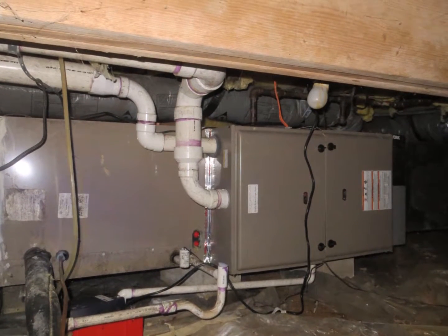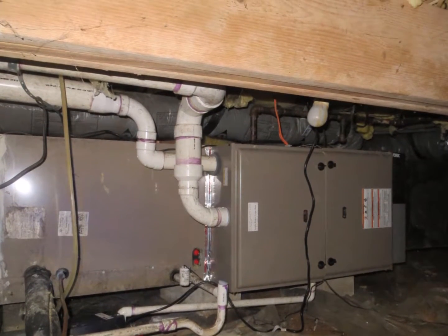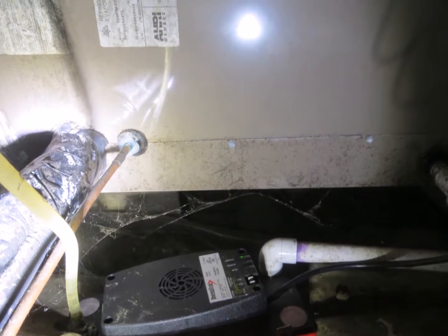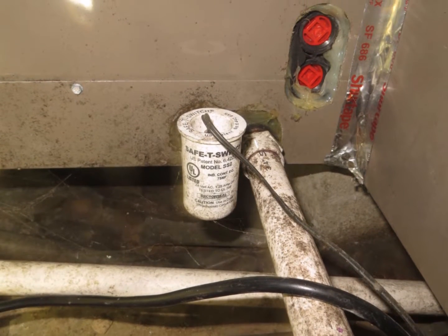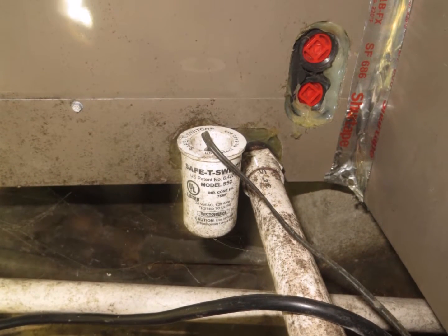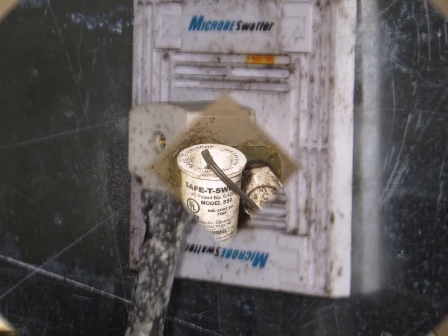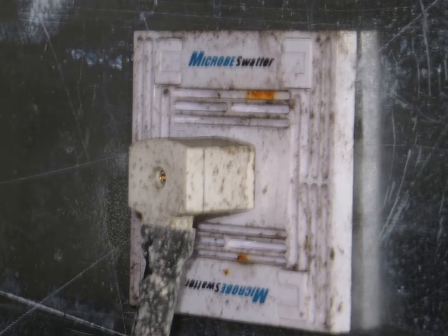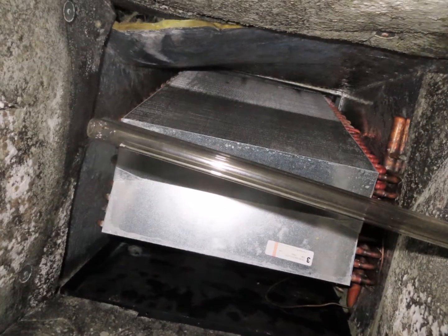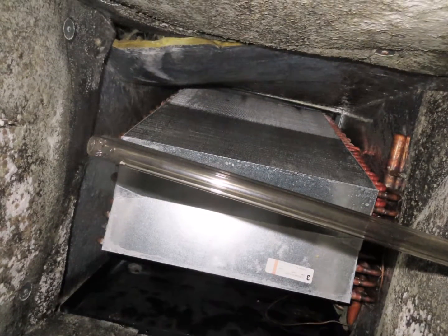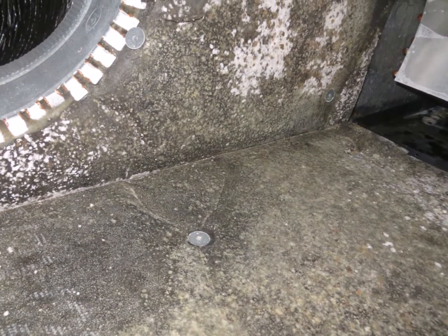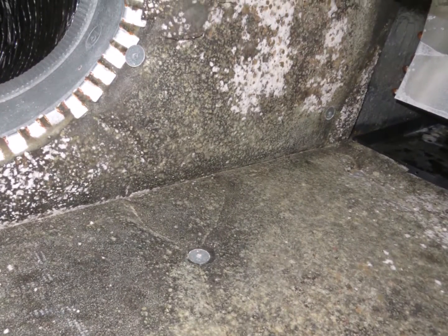The air handler in the crawlspace looked good. On close inspection you can see mold growth on numerous areas on the air handler and the plumbing and the electrical. The condensation lines do not seem to be clogged. I believe this is a UV light that is not functional. UV light should not be used in a ductwork that has extensive mold growth in it, such as this distribution box, which is downstream of the air handler.